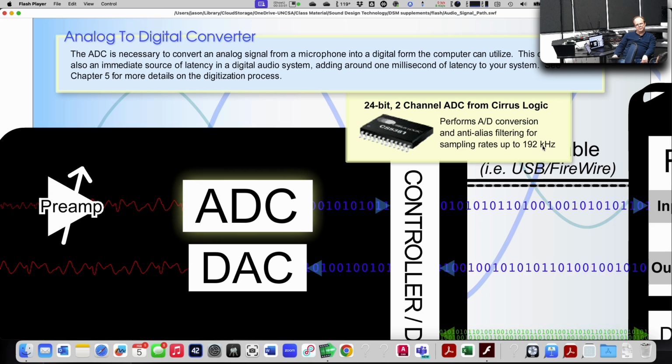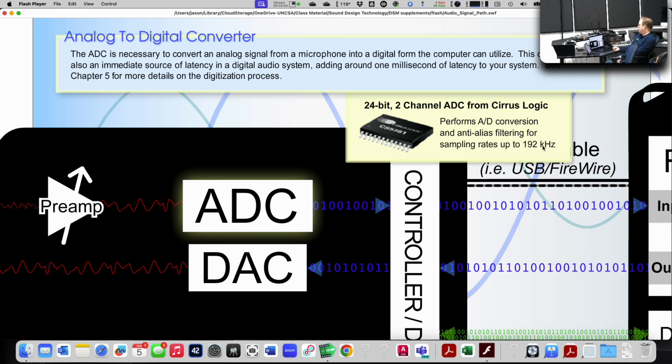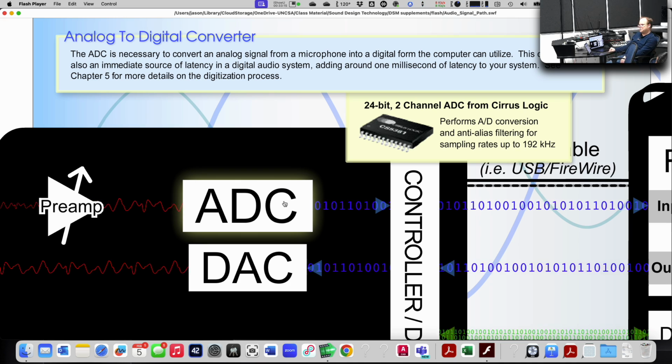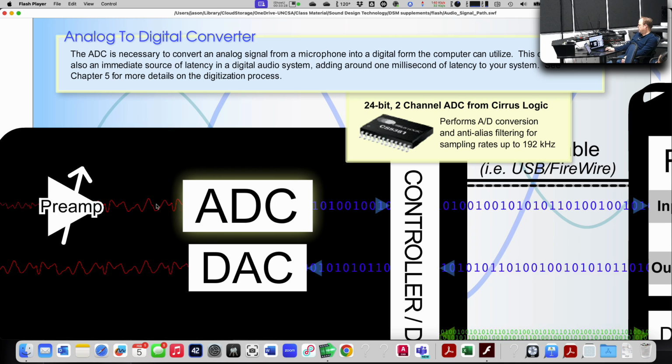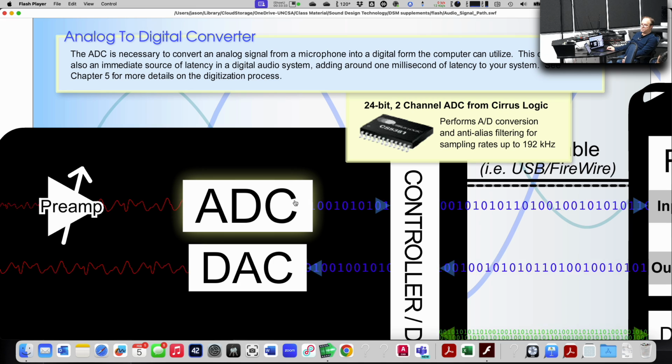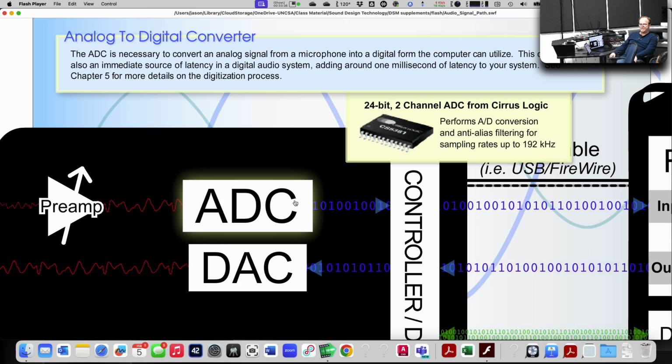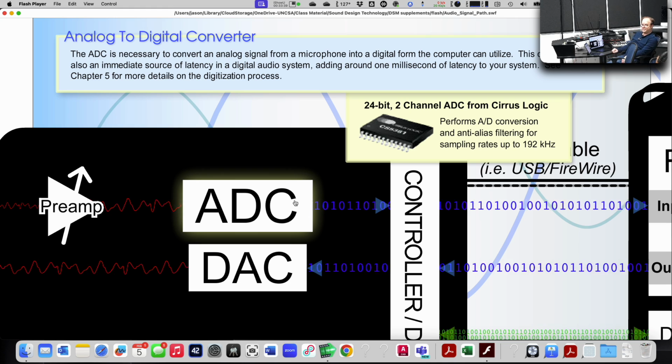But also, there's a latency component to this. Generally speaking, although we're seeing this get faster, these analog to digital converters add a little bit less than a millisecond of latency into your system. So it just takes them about a millisecond to do the thing that they do. Okay? So the analog audio that goes into it comes out of it in digital form a millisecond later. Although we're seeing it get faster now. I've seen some that are as fast as 0.4 milliseconds, which is pretty cool.